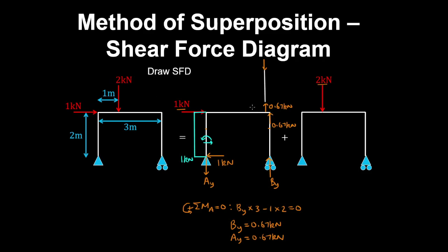And now if we cut the beam from right to left, the shear force is negative and constant across that beam at minus 0.67 kN. And if we cut this column, the shear force in the column is 0, because there's no horizontal reaction at the roller. Now for the second case, you can also find the reactions for the pin and the roller